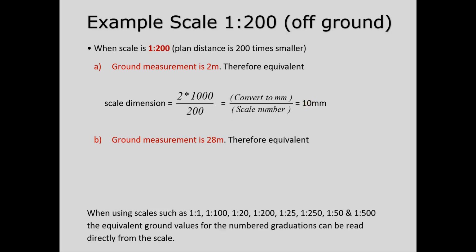So all we did was multiply by the scale. We divided by the scale number. Please do not be confused. The actual scale is 1 to 200. That's your scale. We multiplied by that, 2000 multiplied by that, but in practicality we divided by the scale number. I don't want you to memorize that we're dividing by the scale number, because things will be a bit more complicated in a minute. But generally speaking, this is a starting point. Do not dig too much into this. Let's move on to the next point, and that will give you a clearer idea of how to deal with these numbers.